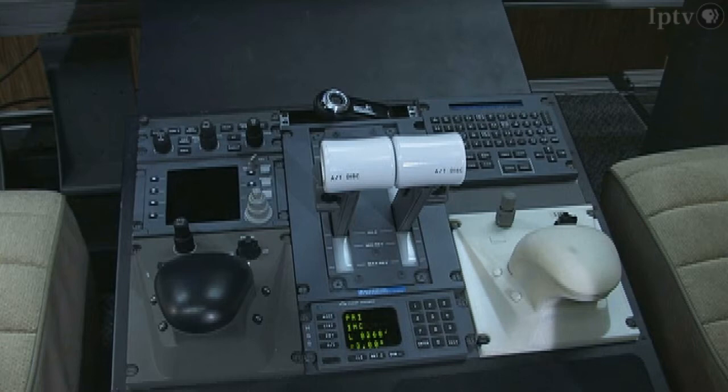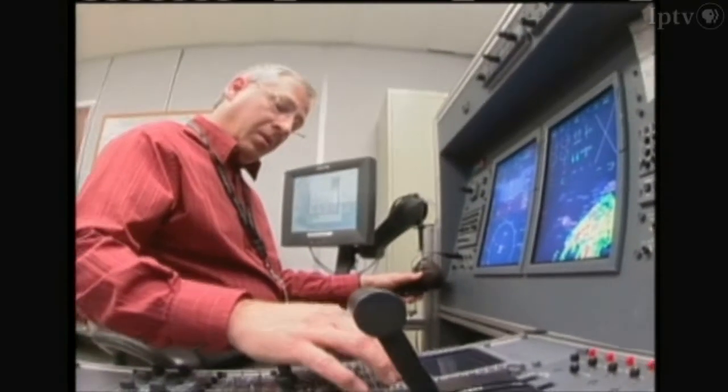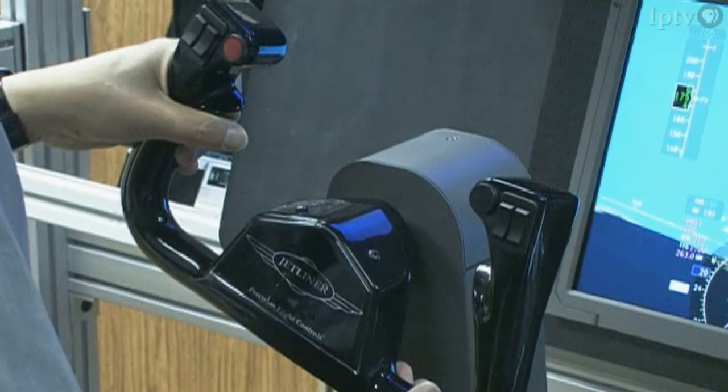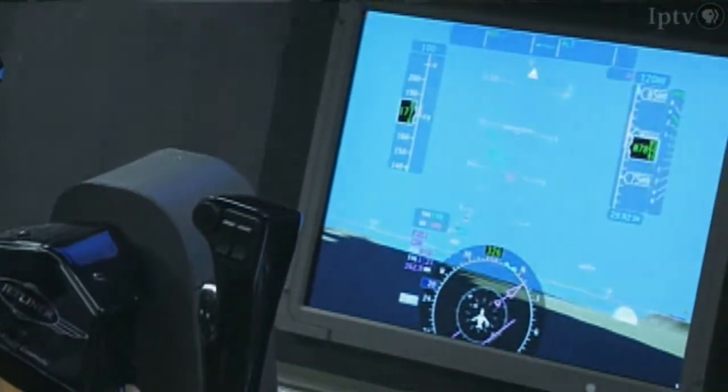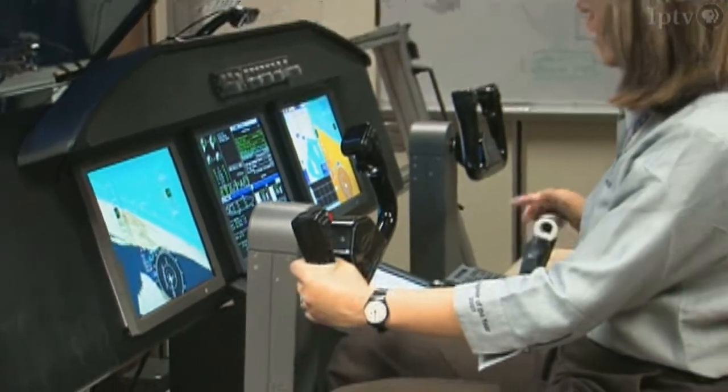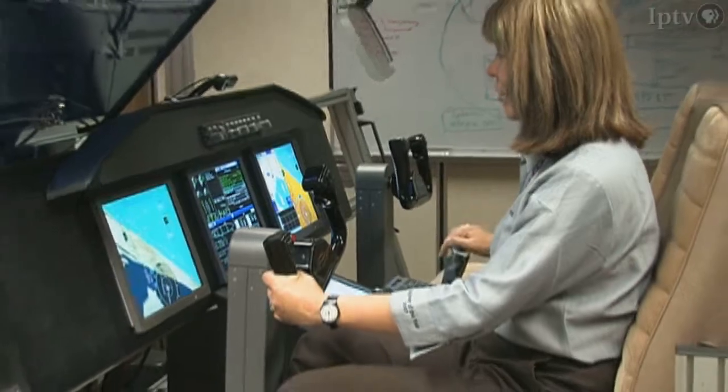We attach the controller in the RFD in a position as close as possible to the actual location in the aircraft cockpit, and then we use real pilots to test out the component. We test the buttons, knobs, and trackball for reach and response. This testing is important to ensure that the component works correctly. For example, the trackball might be slow, laggy, or too fast. At this point in time, it is still easy to make adjustments to the design. Once the component has successfully passed the requirements, it is ready for delivery to the client.